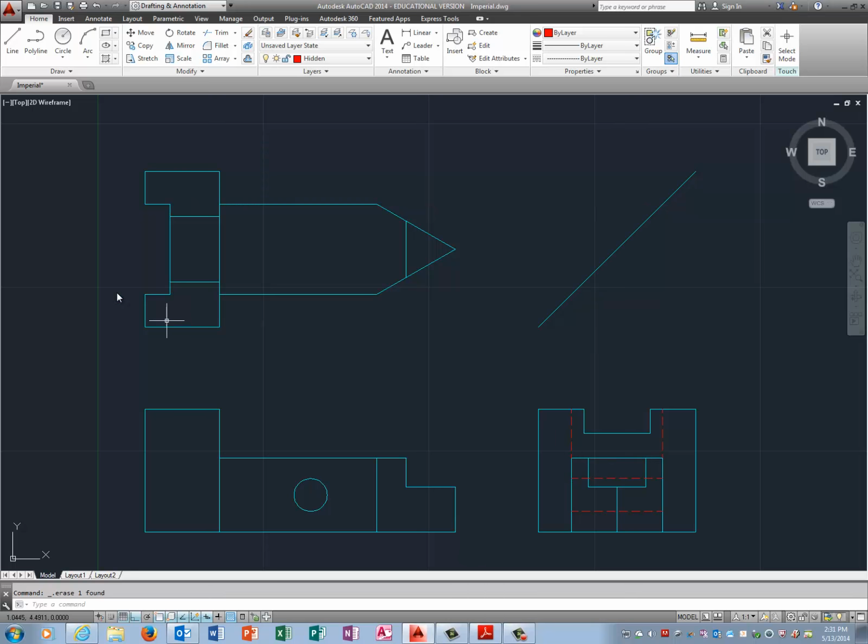Okay, so let's do hidden lines in the top view. Once again, get your quadrants, go straight up. Get your quadrants, go straight up. And we're going to project this corner down because wherever you have a corner in one view, you're going to have a line in another. And then this guy comes across to meet his friend, because that's the little seat and this is the slot.